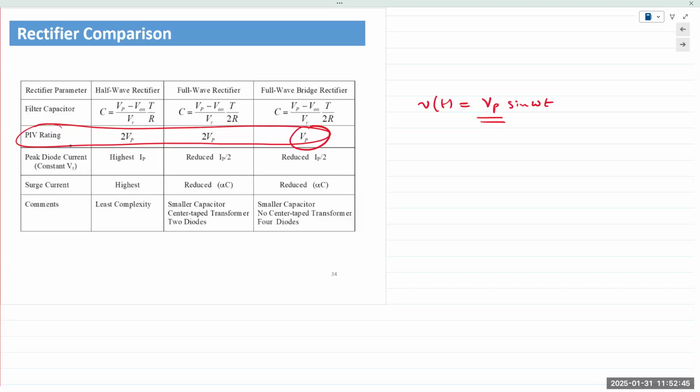At the front end of every device that we ever use. No, no, no. Let's say we have our smartphones, we have our laptops, right? So laptop adapters are heavier. There's a lot more going on inside a laptop adapter. You know, there are switch-mode power supplies and lots of different things in there. But the reason it's heavy is because there's a transformer in there. Mobile chargers, like tablet chargers, are not as heavy because there's a different kind of circuit in there where we rectify directly first, then we step it down, and then we convert it back into AC at a high frequency.